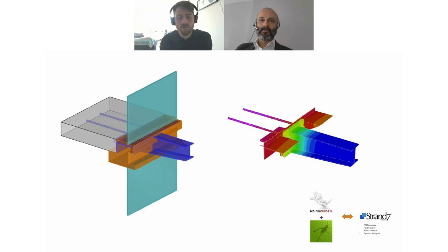across the teams, and more recently, a couple of years back, we developed this further to enable us to model thermal models accurately. So here there's an example of a geometrically quite complicated penetration through a facade, and we're able to analyze the thermal bridging of this. So we've got cylindrical rebar, we've got a tapered beam, and in most commercial finite element thermal software, modeling this is quite laborious. But obviously with the amazing geometric capabilities of Rhino and Grasshopper, and then our tool that we developed, we can transfer that geometry across quite seamlessly.